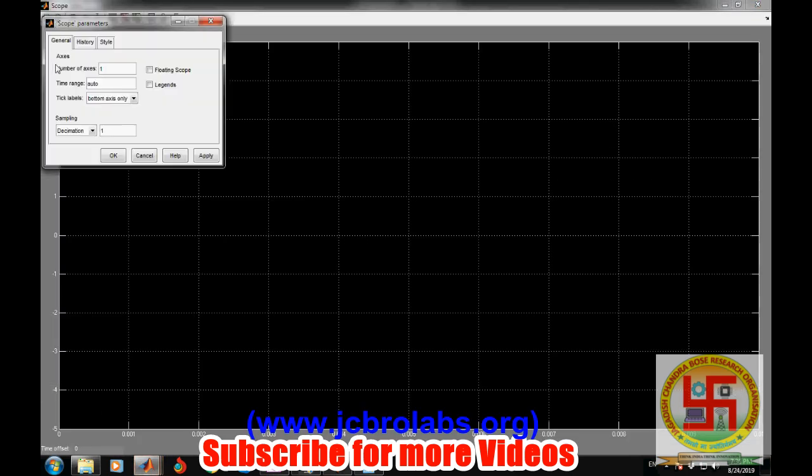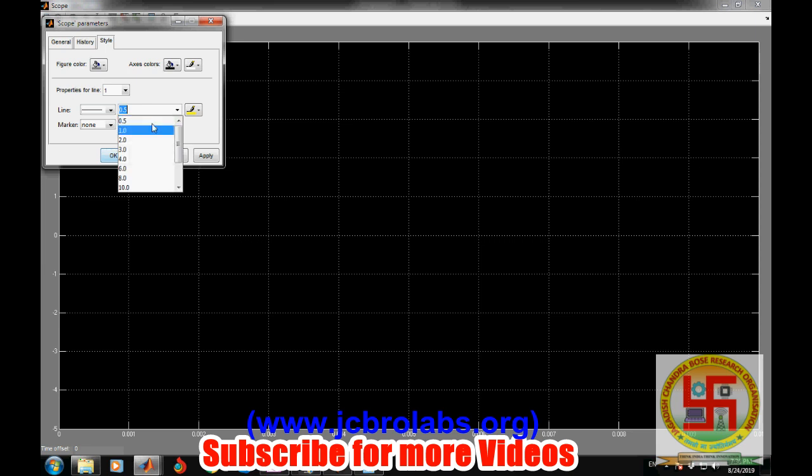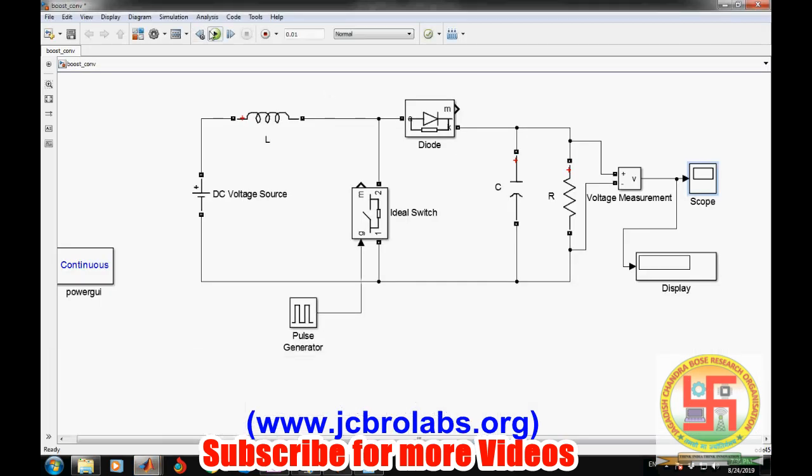Go to the scope and let's change some properties of it. If you want to visualize the complete graph, remove this limit, and in general we will increase the line size of the graph. Let's make it 2. Apply. Now let's simulate it. Remember, we are simulating only for 0.01, and if everything goes fine, it will simulate.